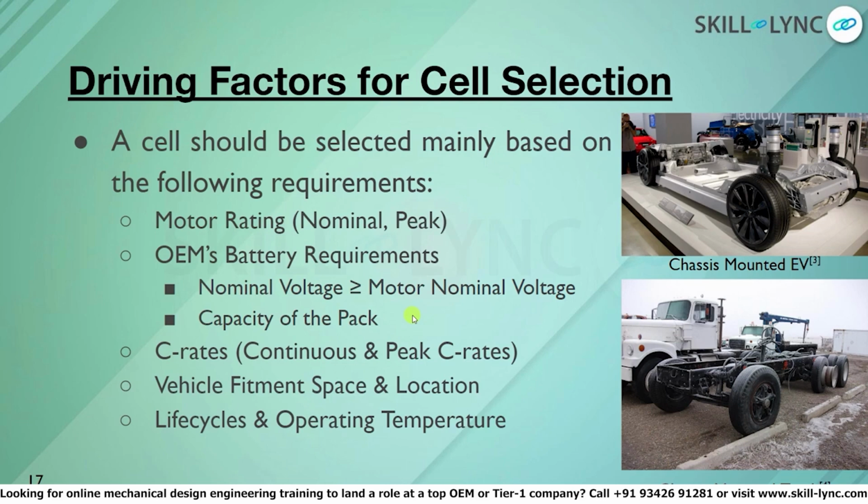And then once the battery pack voltage and battery pack capacity are decided, the most important part that you need to understand is the vehicle C rate requirement. What is the C rate requirement needed for accelerating the vehicle, when you want to overtake, when you want to go at higher speeds? And when you say accelerating, which is the discharging current, and when you accelerate and move faster, it becomes peak current.